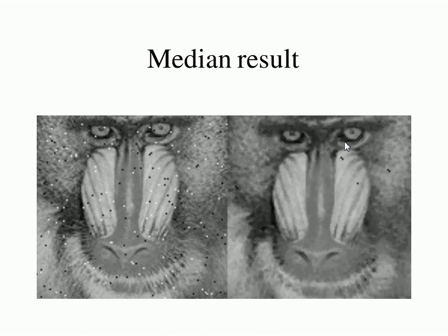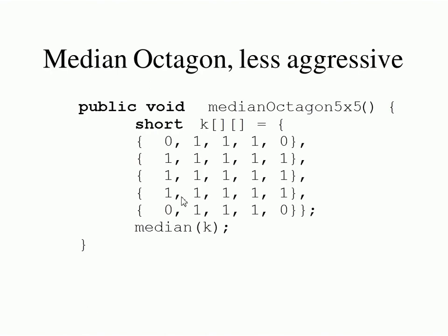I mean, that median filter does a reasonably good job. Right? Look at the shot noise on this image, and then look at it afterwards. You could still see some pock marks right in here and in there, but in general, the single pixel shot noise has been eliminated. That's not bad, right? Impressive, actually. I mean, imagine if you had to do that yourself, right? Fill in the little dots with some sort of pixel manipulation program.